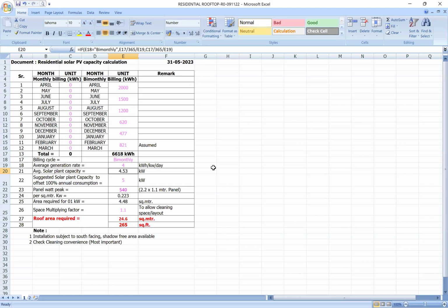then a further 50,000 rupees a kilowatt peak is the cost of battery systems. Now, to charge the battery system, there is a conversion ratio, right? The efficiency is 90% on bidirectional. So when we charge using our solar generation and then discharge it, 10% losses happen both times, so about 20% losses, approximately. Case to case we have to see. So out of that, only 80% will be available for you.